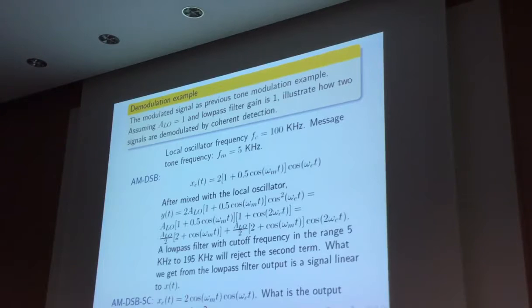Okay. We have the signal after the mixer, right? At the receiver, which is represented by y(t). So mathematically, it should be the AM DSB-SC modulated signal x_c(t) multiplied with the local oscillator signal. Right? Okay? So this is the expression for x_c(t) according to what we learned from AM DSB-SC. Okay? Synchronous case, right? Synchronous case.